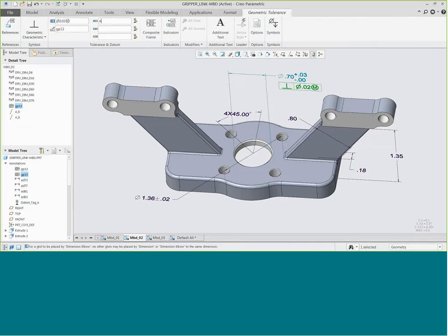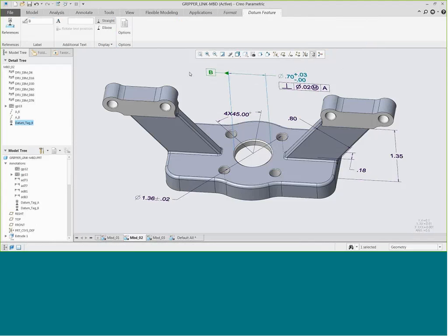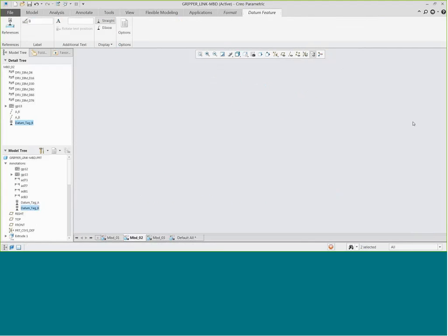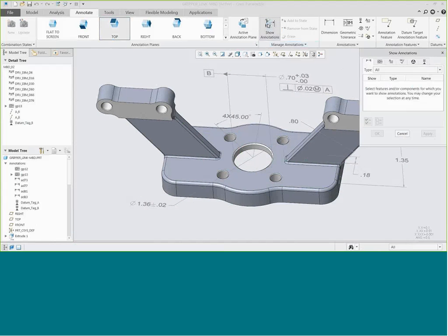So we're going to state what we want it to be relating to, and you can see then that in that menu box it actually came up green, and that's because we already have a tolerance tag that is created called A. So in addition now that we've created this perpendicular hole to that flat face at the bottom, I'm going to give it the reference tag B, and then I can go and compound these tolerances in additional geometry on the part. So let's go to an alternative view now and start to look at these holes on the base.